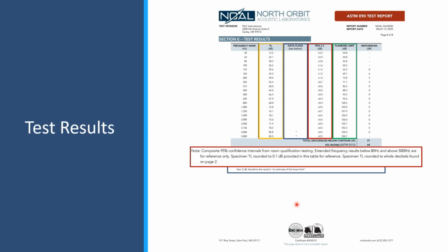So you make noise in one room, measure how loud it is in there, and then go measure in the other room on the other side of the partition that you're trying to test, measure how loud it is in there, take the difference, and then do some kind of math according to the standard.